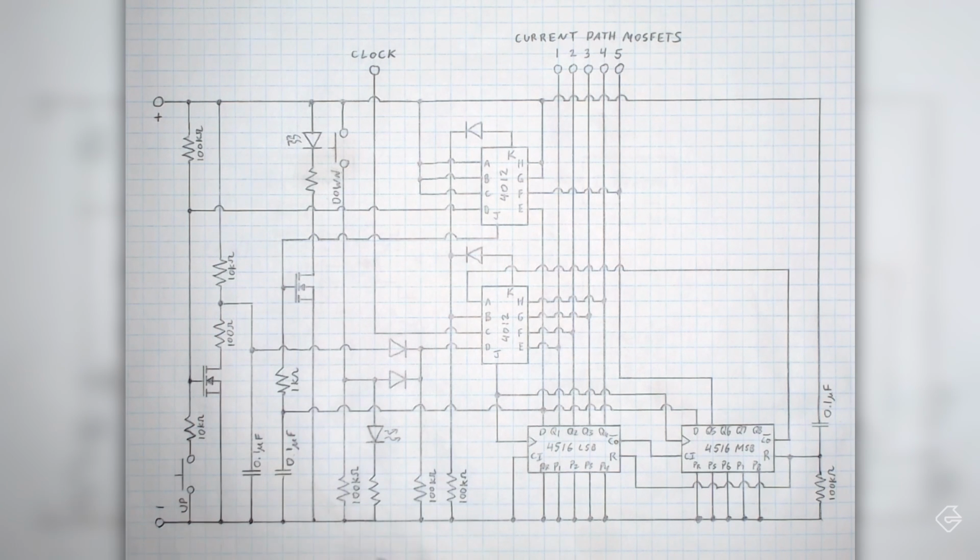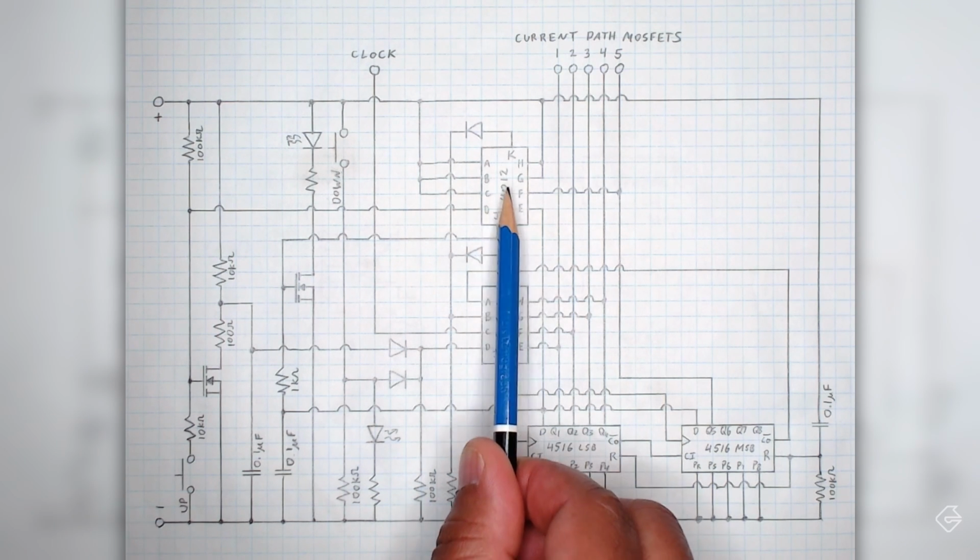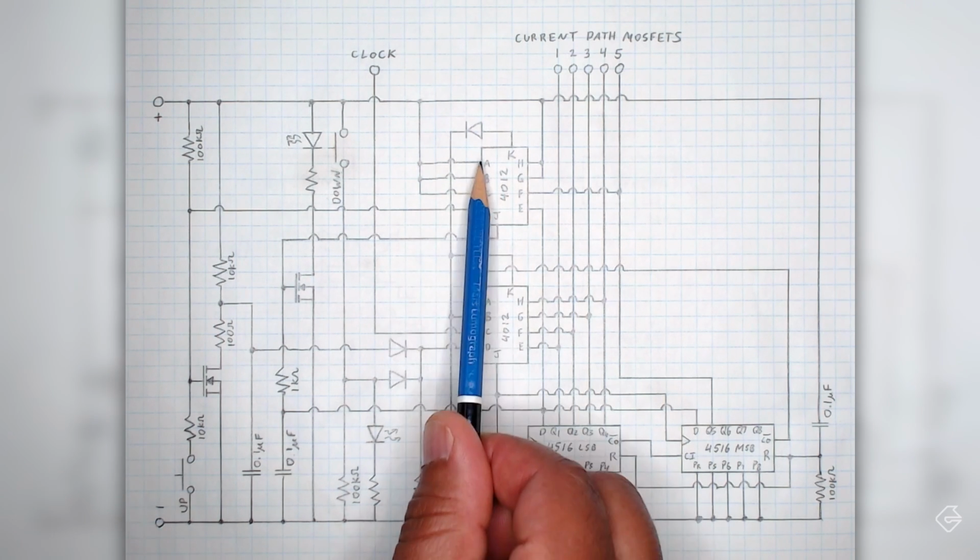Now, when we designed this schematic, what we needed at the time was a CMOS inverter. Again, go back to one of the older episodes that I'll link if you want to understand exactly why we needed a CMOS inverter, but the fact is we needed one. And it just so happened that when I was doing this schematic, I noticed that half of this chip, the 4012 chip, was unused. This is a 4-input NAND gate. So I was like, this is super convenient. Let's use this as our CMOS inverter. And so that's exactly what we did.